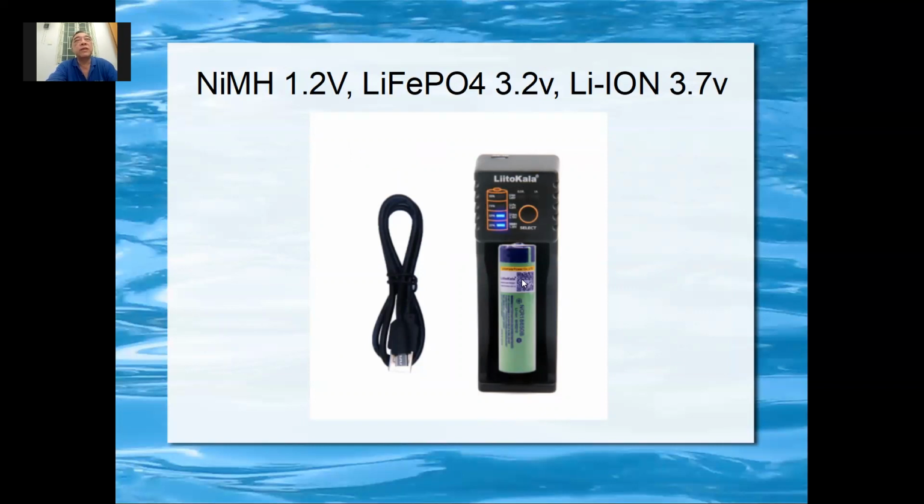It auto detects, it will charge. So if it fails to auto detect, because sometimes your battery voltage is too low, very long didn't use for many months, and then the voltage discharges until too low, then it cannot recognize. Then you press this button to select which type of battery it is, and then it will charge to that battery. Normally you just plug in, and it will detect whether it is lithium ion or lithium iron, and then it charges accordingly.